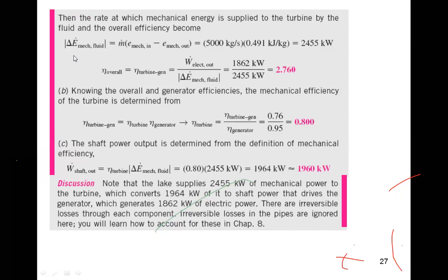So this is calculating the efficiency part. Here you have the mass flow rate. This is what you got previously from the mgh term, which you multiplied here. Then you are taking the electrical work, because you are taking 95% efficiency of that. So you multiply this value by 0.95, and then you got this value. So this is the overall efficiency of that particular turbine.